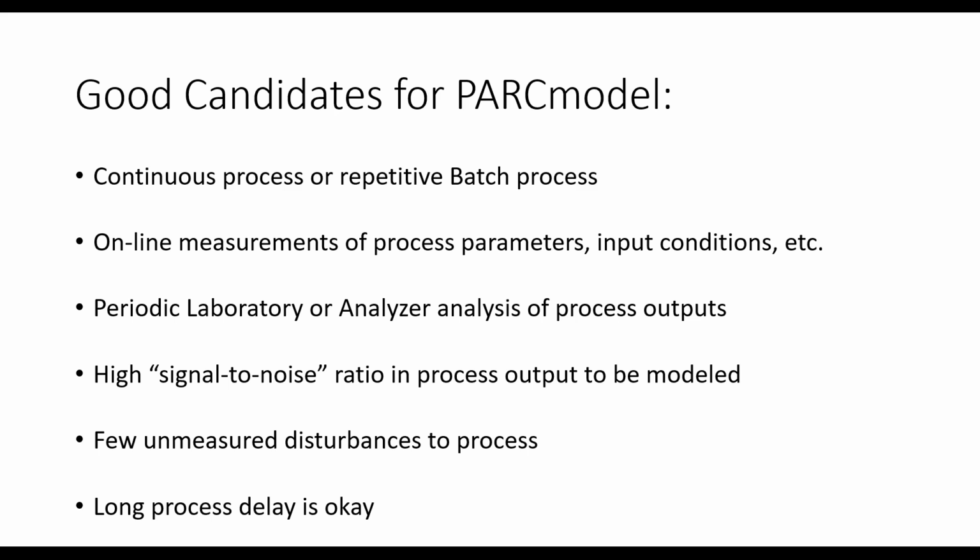do modeling with it. One thing you want to look for is a process that has a significant number of online measurements of the process input parameters, or the conditions of the input materials. You don't have to have everything measured online in real time, but the more of that you have, the more likely you are to be able to build a good real-time model.